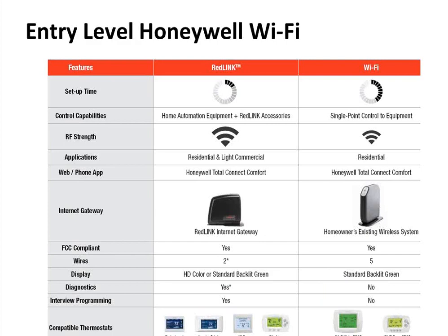Dale asks, are all systems expandable for multiple zones, such as 14 zones of heating in a hydronic system? Yes, all of these products could be used for multiple zones in the same house. They all do it a little bit differently. Like the Honeywell ones, you'll have one of these Redlink gateways, and all 14 of your zones would talk to that gateway plugged into your home router. Whereas the other products, each one of them would talk wirelessly to a router.